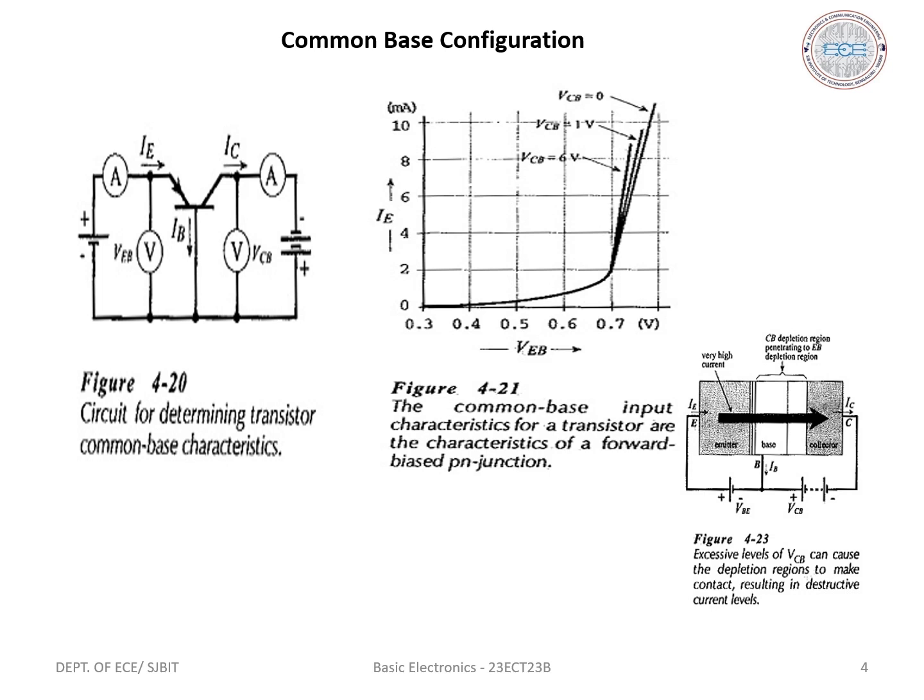The input resistance Ri of the transistor in CB configuration is defined as Ri equals delta VEB by delta IE. As the change in emitter current is very large for a small change in input voltage, the input resistance is small.